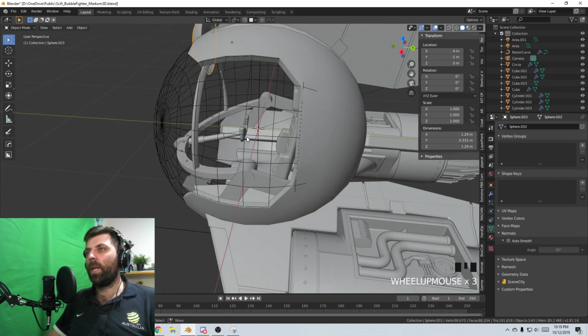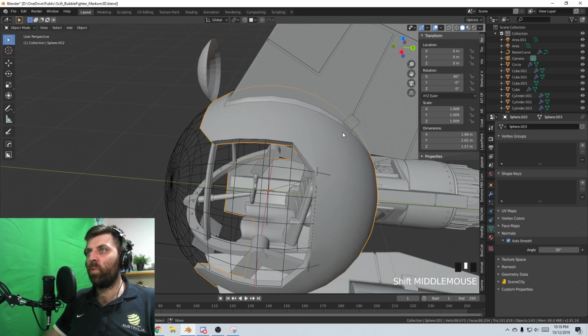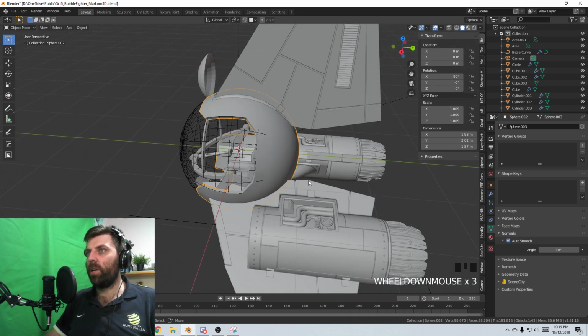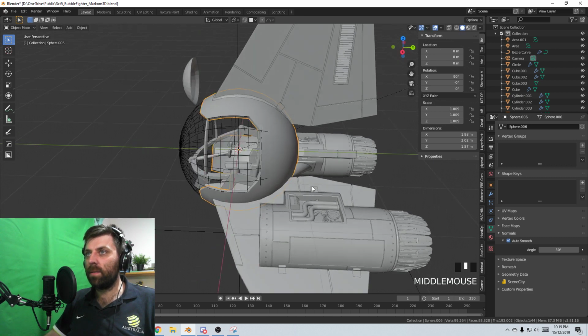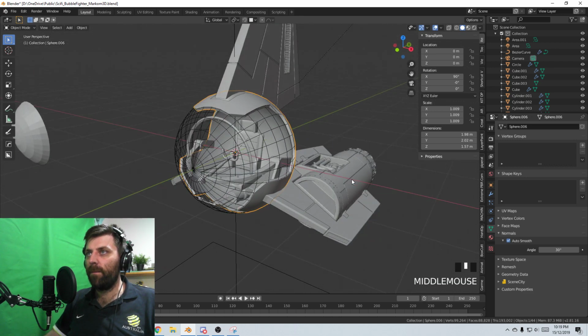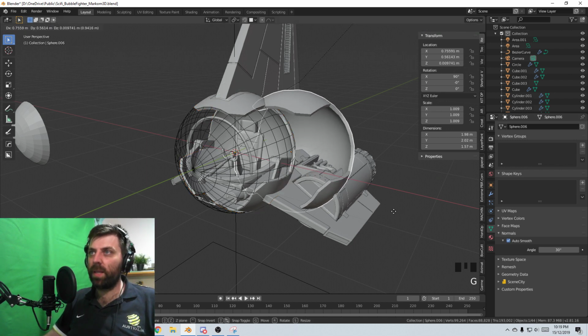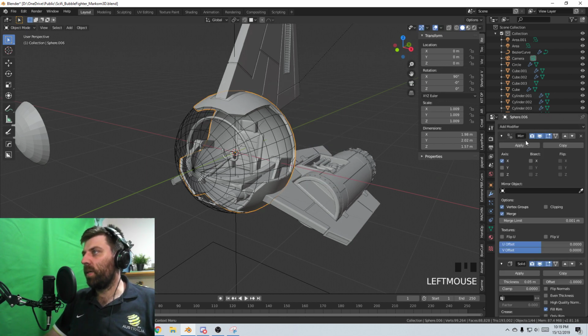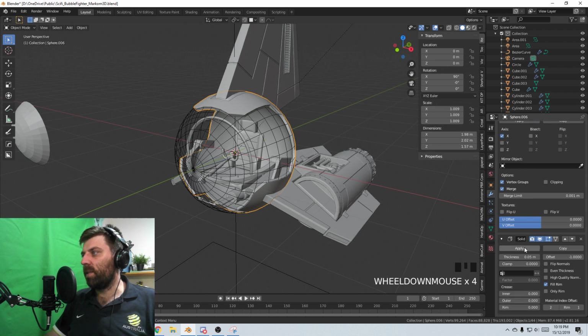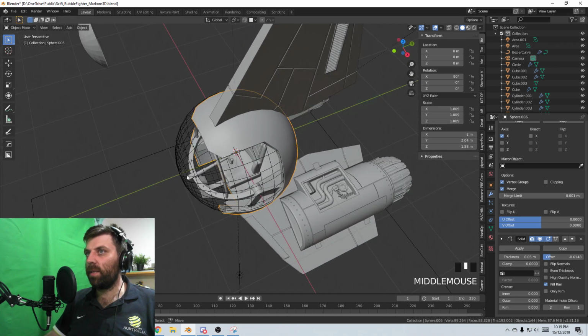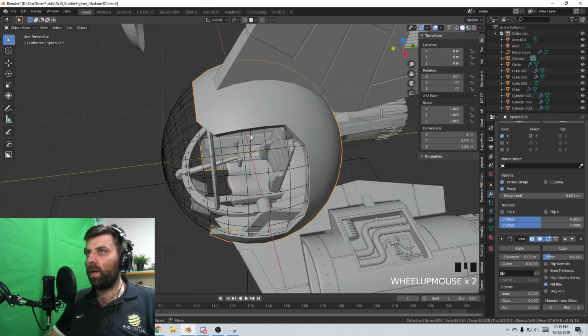You know what? Let's come back. Let's work on maybe the shell here. So let's go Shift D to duplicate. Did I duplicate that? Yep. Let's come into here, mirror modifier, solidify. So I'm going to make that, which way? Expand a little bit. All right.